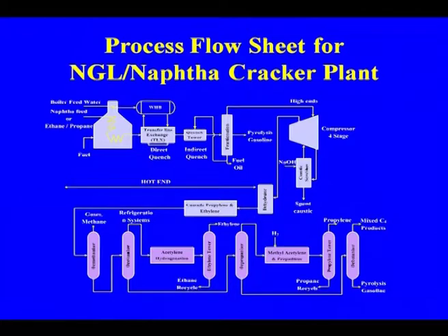This propylene again goes for various uses, and the propane product is recycled, and as I told you, the propane that we are using is in the refrigeration cycle. Similarly, the bottom of this column goes to another column, what we call the debutanizer, for the mixed product C4 and onwards, because that will be obtained from the pyrolysis. This C4, the recovery of the C4 C5 gases from the cracker and the FCC, we will be discussing separately.